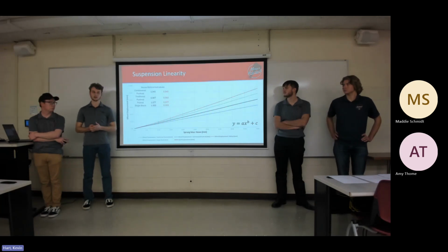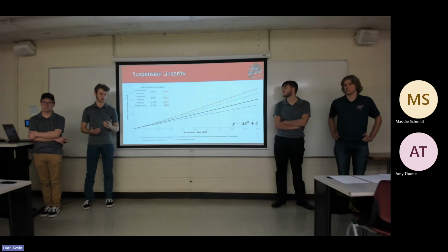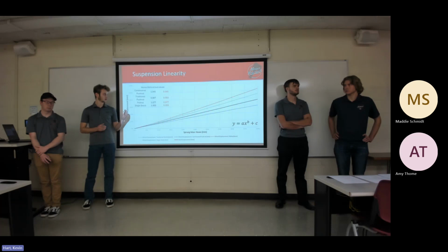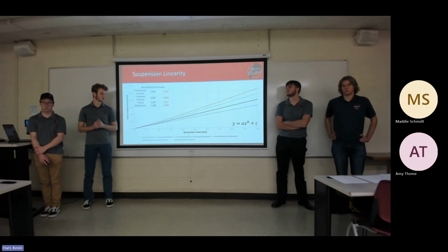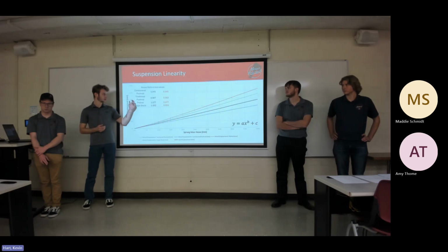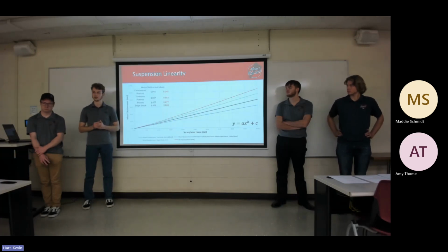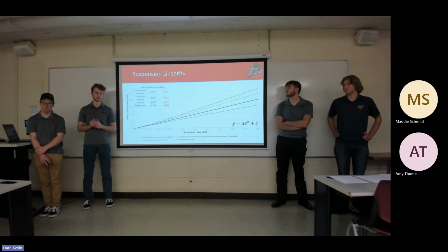The single shock is inherently the most linear, as there's only the shock and the angle of the shock making the travel nonlinear. And then for the other designs, we looked at which one is furthest from 1 and it got the least weight. And then between these two similarly distanced from a power value of 1, the digressive was weighted more poorly than the progressive, as ideally we'd like the suspension to become more stiff rather than less stiff throughout the travel to prevent bottoming out.